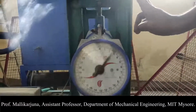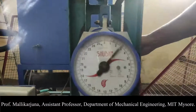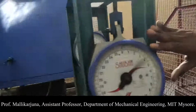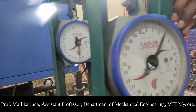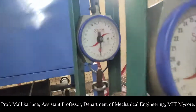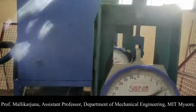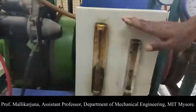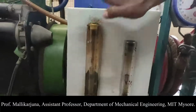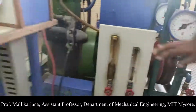Okay, now the load on the engine is varied. On this side and on the other side, the values need to be subtracted. So here we have 4, here we have 12. So 12 minus 4, 8 is the reading. That is the load on the engine. These 2 values are fixed. We are not going to change the amount of water supply to the engine as well as to the calorimeter.